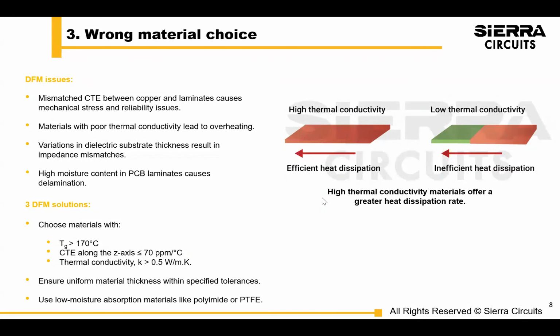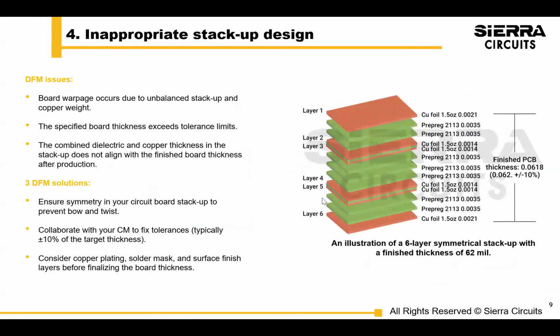If we pick a material that's cheaper and doesn't have good dimensional stability, it's really just messing up our own scaling database. And then the customer would also get unexpected results. So picking the right material, both from the customer standpoint and from the manufacturer standpoint, is a key part of the DFM. Once you pick the material, did you also pick it for the stack up?